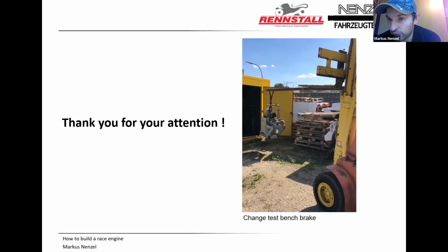For your gas exchange, your simulation and your waves, the primary pipes are quite important. With a 4-cylinder engine, for example, the secondary and tertiary pipes have not so big an influence, and you can buy a muffler because it works, it's lightweight, and you have a good back pressure.